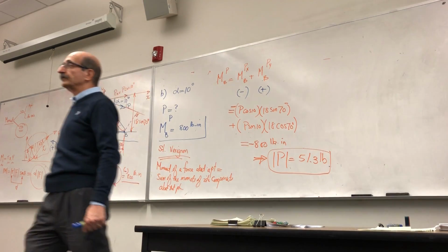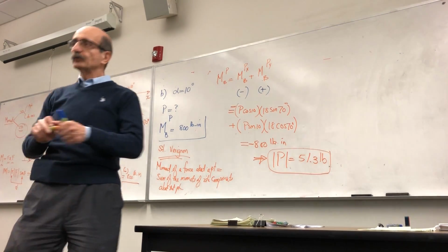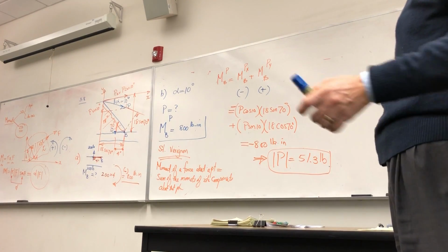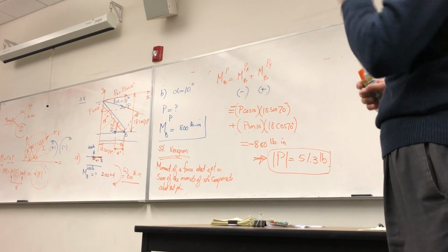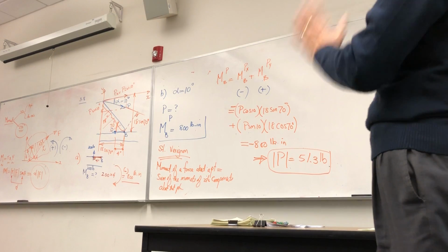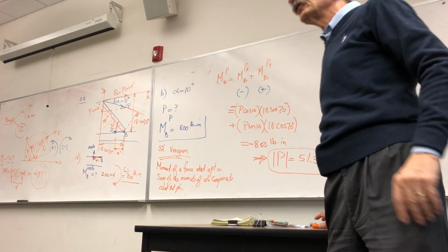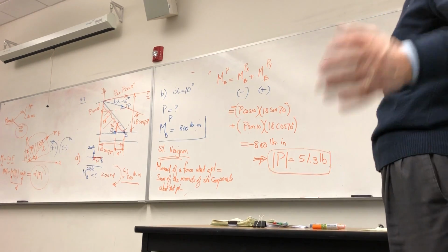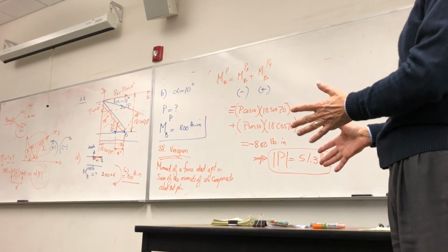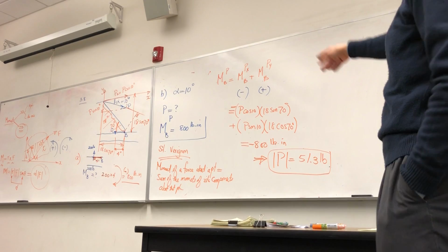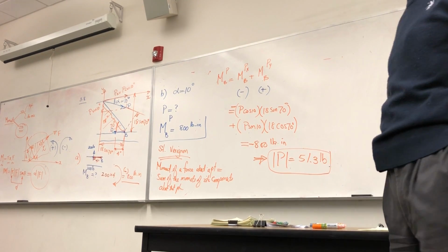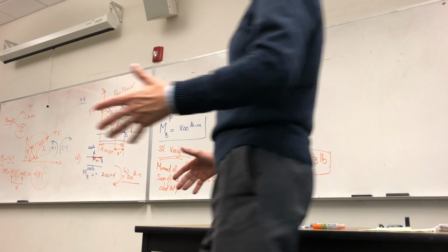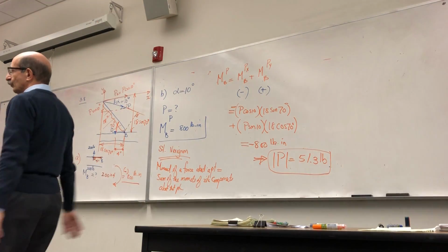This concept of St. Varignon, remember that, because we will be using that throughout the entire course from now on. Always think about it. When you have a force, resolve it into its components, find the moment of the components, add them up. That's a whole lot easier than dealing with a force in the general direction. Okay? So you have all the ammunition you need to solve your homework problem.